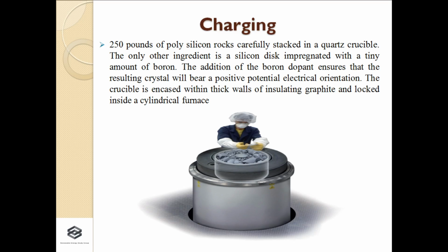So whenever we construct the lower layer of the silicon cell, it is made up of the P type semiconductor material, and to make the P type semiconductor material we require boron, which is the acceptor impurity we are taking here. In its outer shell there are a total of 3 electrons, and by accepting 1 electron it will form a stable covalent bond with the silicon material.